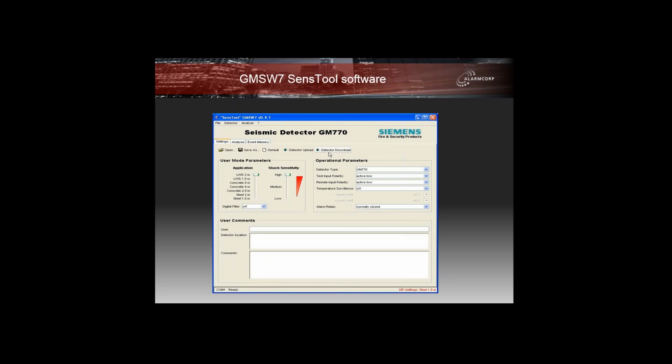Those things are going to take many minutes, and the detector would pick that up within 15 or 20 seconds, which is its limit. But if it was blown up, hit by a car, or hit by a sledgehammer, that shock sensor would generate an alarm immediately and activate the relay.